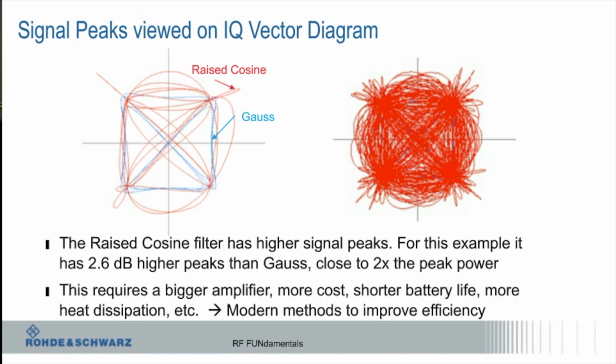You hear that a lot in more linear modulation schemes, but it's basically that I have to drive that thing with more current. So it is less efficient if I'm running it to take a higher peak to average signal. The raised cosine filter scheme has the highest signal peaks, and the power amplifier guys aren't so happy with that. They don't like it.